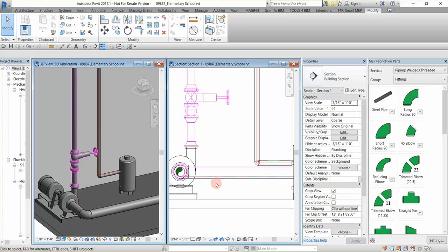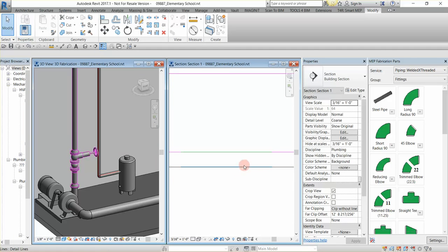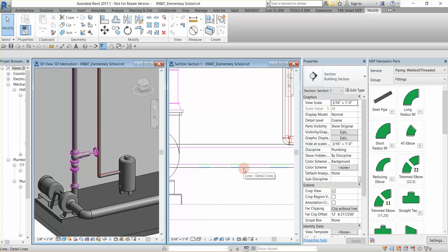If I were to look at this 6-inch pipe in that fabrication database, it's actually jumping to a different thickness automatically, and that's actually 1.25 inches. So again, just using these detail lines to show you that thickness that's in there. So this is set up basically with some rules inside of there. I don't want to use the word code, but we could potentially set up some rules in there that automatically assigns an insulation thickness based upon the size of pipe that we're running.